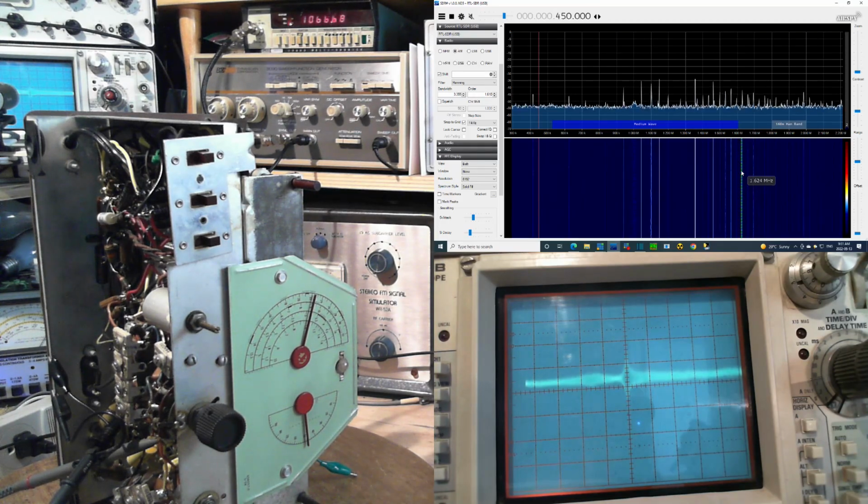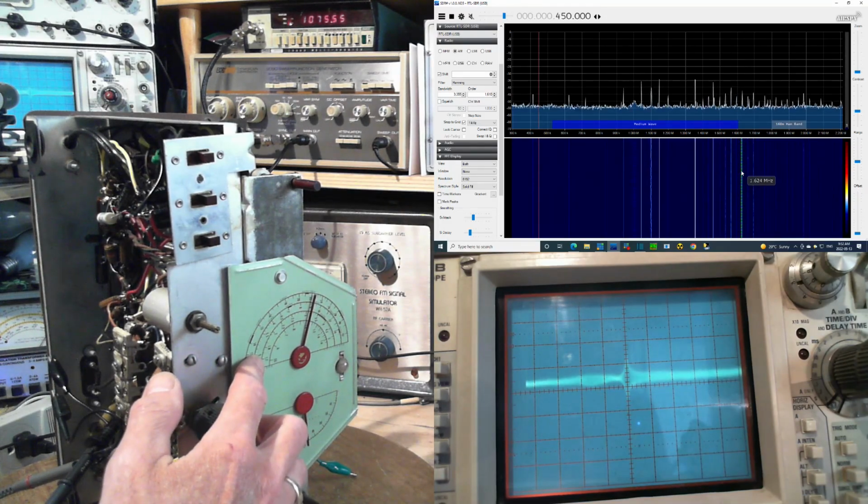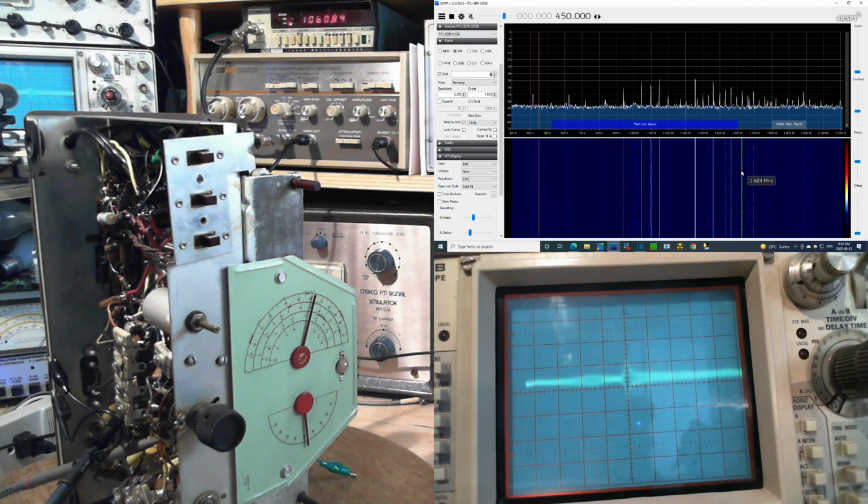let's think about this. Now the oscilloscope is looking at the output of the IF. Somehow some signal is getting there that the scope can pick up. I don't know. Does anybody do this? Anybody try seeing what goes through a radio when you don't put power on it? Unfortunately, my sweep is only good down at this band. Actually, I could sweep right through the next band too, because my sweep goes up to 5 megahertz. Oh well, we'll get to that in a minute.